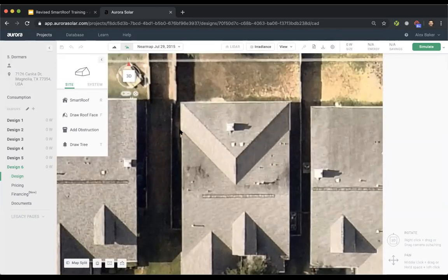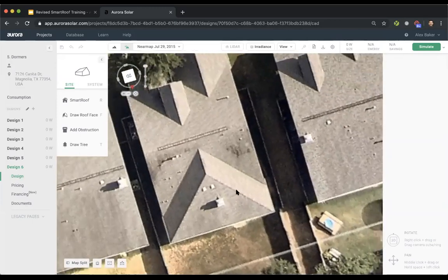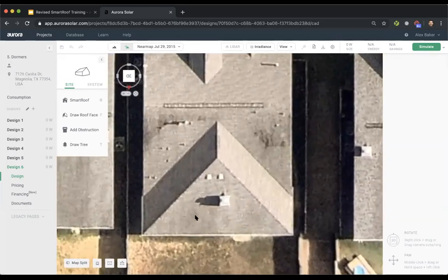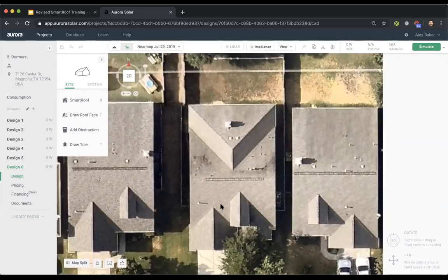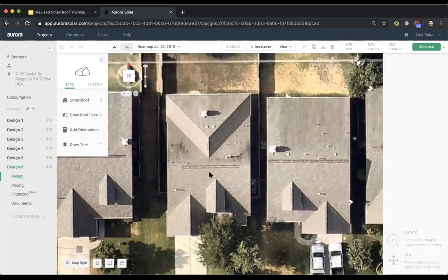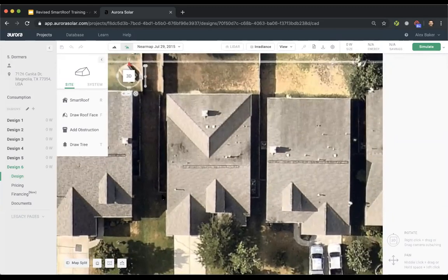We have this extension sort of on the back, but if I'm thinking about the shape of this, it kind of looks like a hip dormer because we have 3 slopes on the dormer. So I think to make this drawing easier on myself, I want to go ahead and just add this as a hip dormer instead of drawing the entire roof perimeter. So anytime I know that I can add in dormers, I'm not going to worry about the front corners in the shape. I'm going to keep my shape really simple.